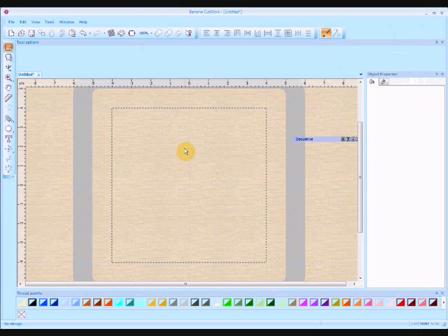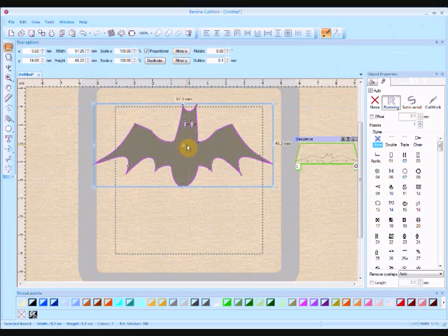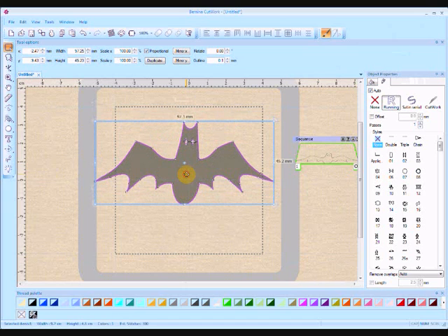I'm just going to close that because I'm not going to save any changes, and okay with that hoop. Alright, now I've got my hoop in place, and all I'm going to do is come up here and I can paste my graphic in, and here it is. So that's a quick way of getting a graphic in, and it will bring in a few more formats other than those listed. So if you're having trouble getting your graphic in, if it still doesn't bring it in with the paste, it means it's not compatible at all, and you'll have to find a new format for that graphic.